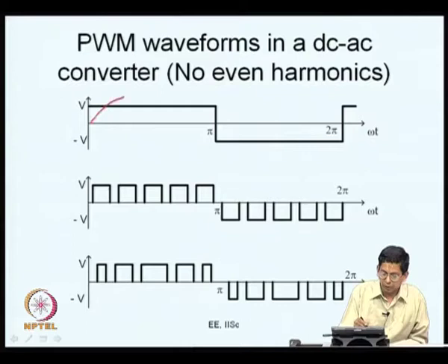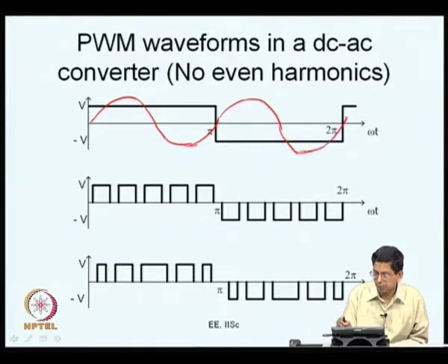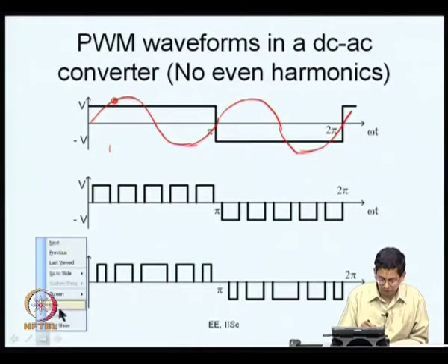Let us say you want to check whether it has a second harmonic. What do you do? You multiply it by a second harmonic as shown here. Now, take some arbitrary instant, say here, and the same instant 180 degrees later. On the same instant, let me just change the color of ink.